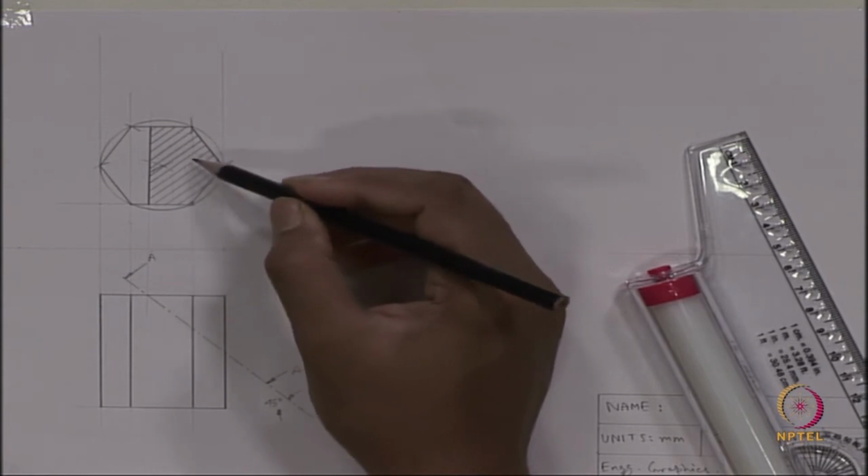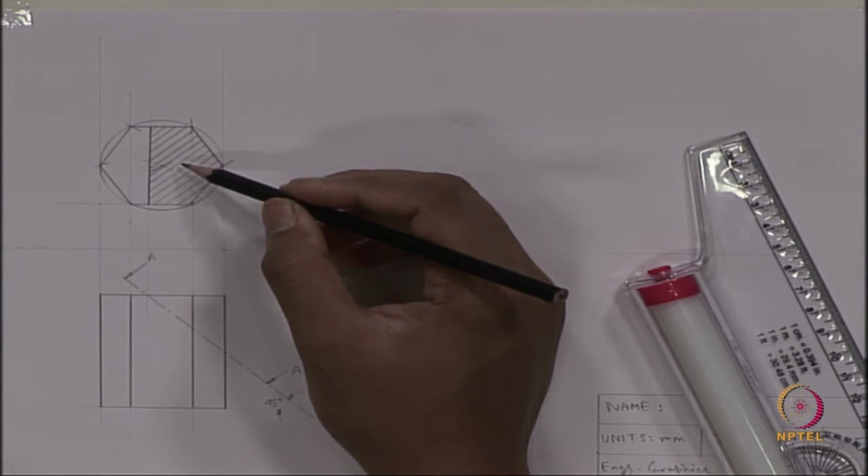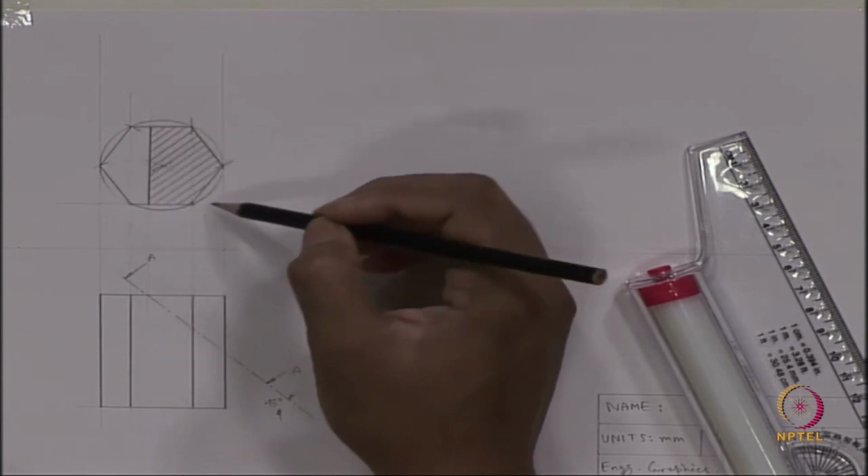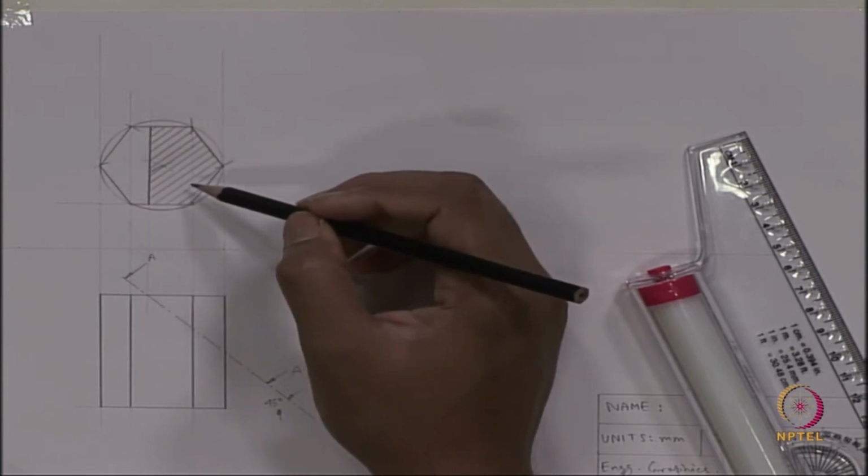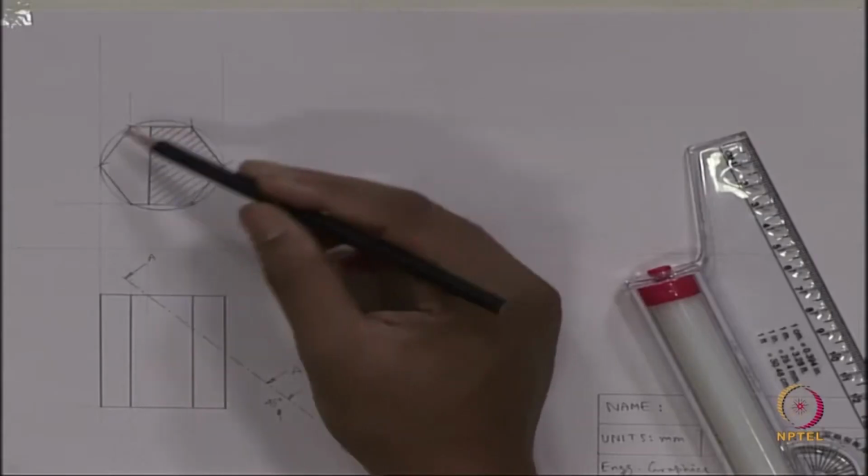This plane is actually inclined, so in the top view we will not be able to see its exact size or exact shape. That is why we want to take the help of the auxiliary view. In this case, the top view will be the related view. So, when we draw the auxiliary view, we will take the dimensioning help from the related view, or top view,